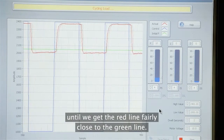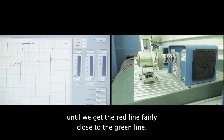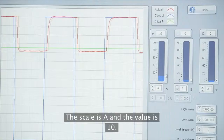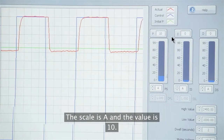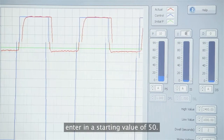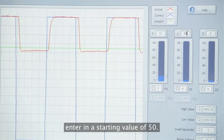until we get the red line fairly close to the green line. So now we have our initial P setting. The scale is A, the value is 10. Now we go over to our I term and enter in a starting value of 50.